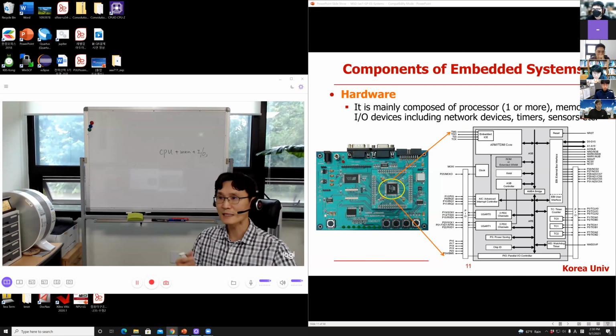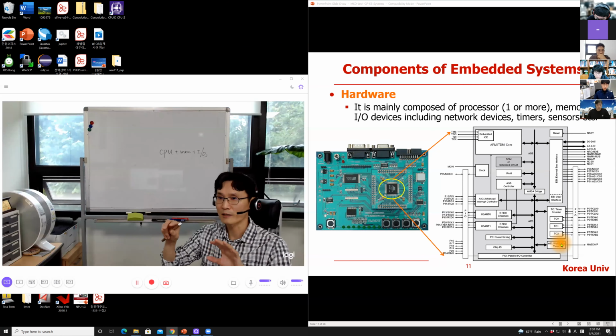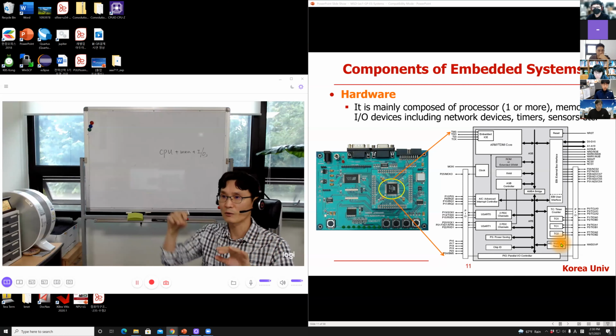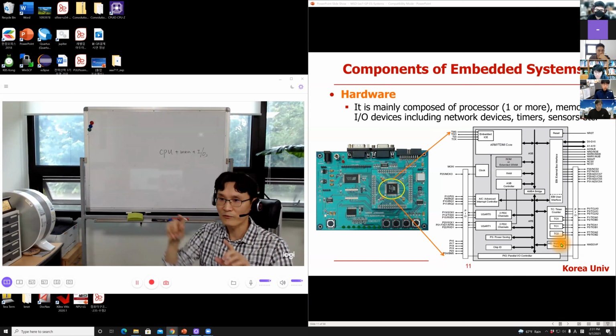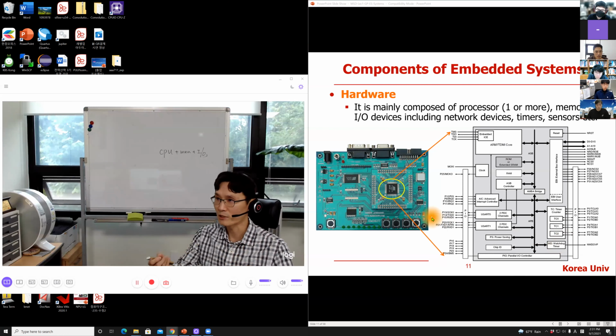Watchdog timer is used to reboot the system, just in case something goes wrong. So watchdog timer is used in applications such as a mission to the moon, mission to Mars, outer space, where humans cannot physically go, and if something goes wrong, you cannot go to the moon or Mars to fix that problem, right? So the main function of the watchdog timer is to reset the whole system. If something goes wrong, the only way to restore the system function is to reboot the machine.